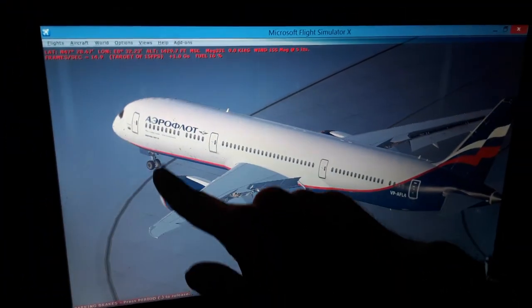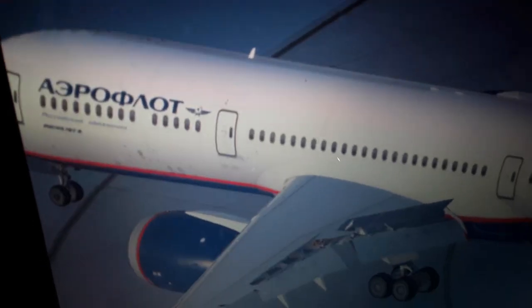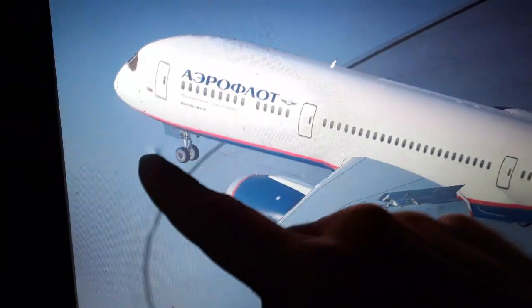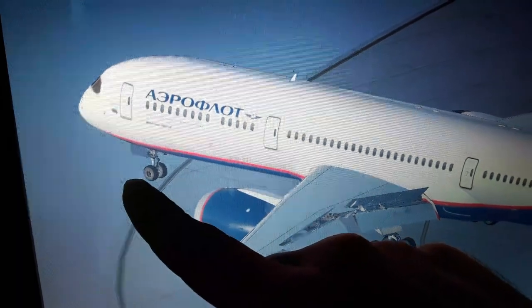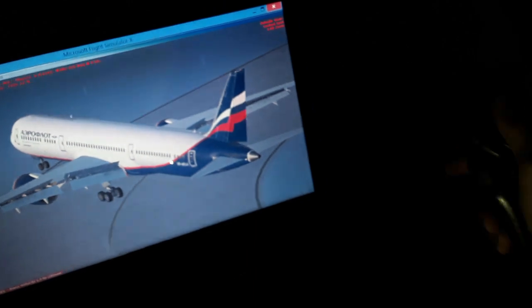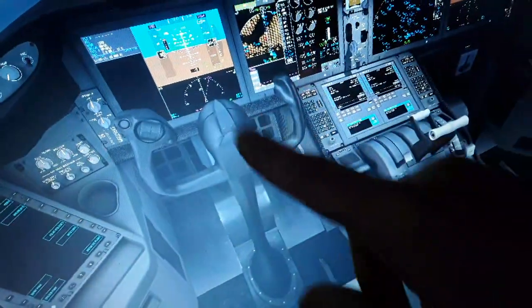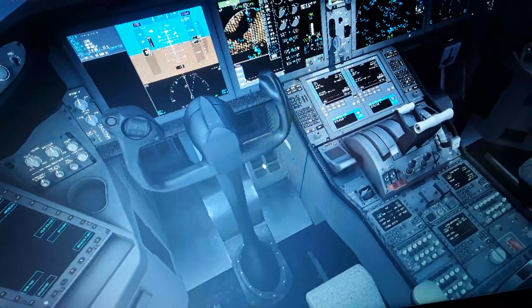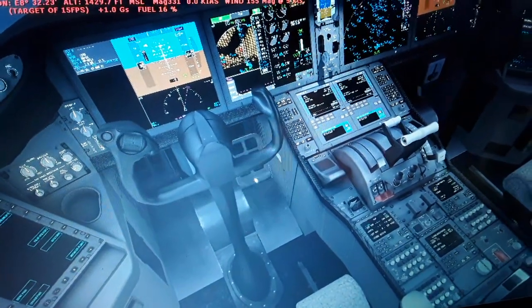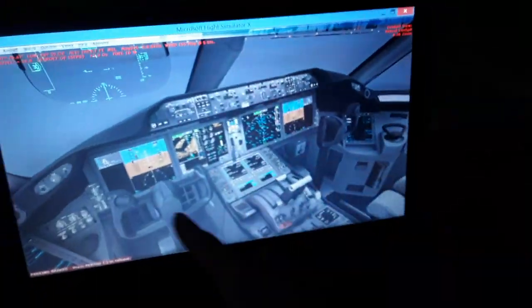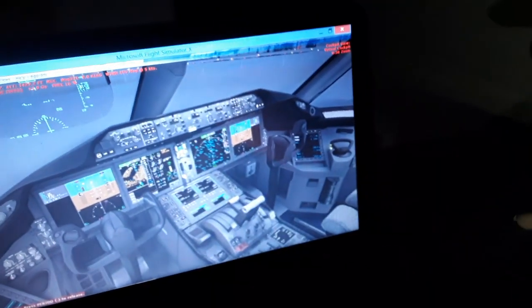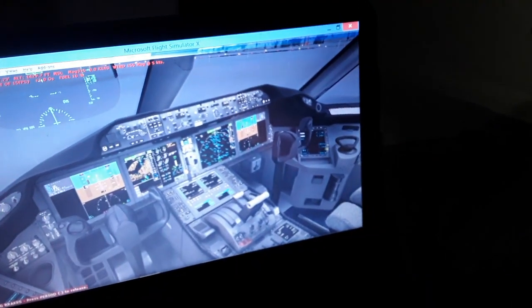You can use also the nose wheel steering on the ground. We can use the forward nose wheel. Depending on the airspeed of the aircraft, you can make left and right turns of 76 degrees, either left or right side, using the rudder pedals together with the rudder control we have over here. The rudder, the vertical stabilizer, and also we have left and right rudder. We have also the nose wheel steering, left and right turns. Both sides are interconnected, move together. There's no difference in the deflection.